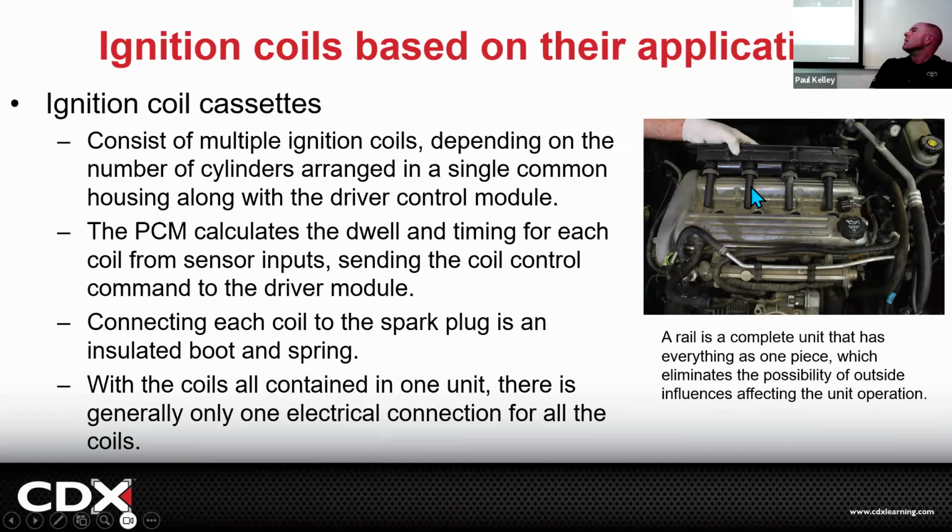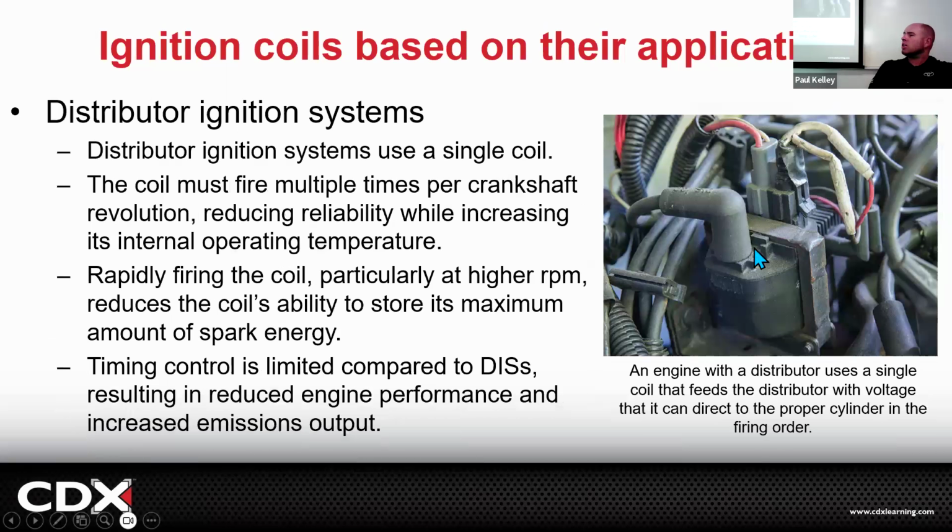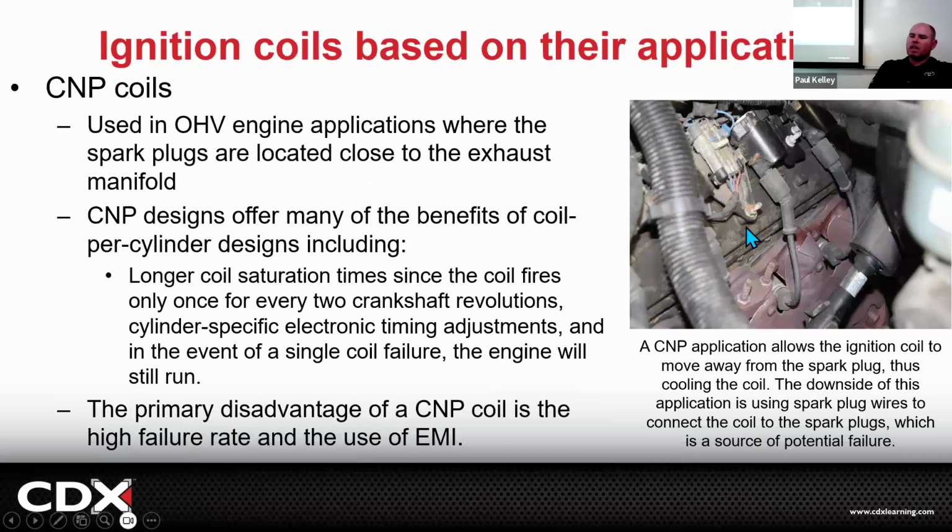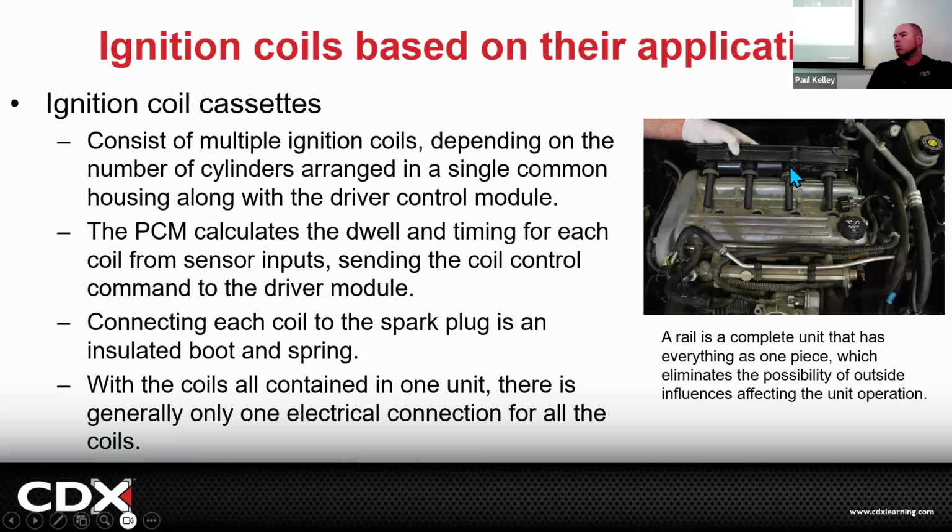And so this one's a little bit of a pain in the butt, though. This might look familiar to you. It's a cassette style. The reason that these were not amazing is because the whole ignition coil and modules and everything were built into the top. So if you had a failure on one, you got to replace the whole assembly, which was kind of expensive. But when it came out, they're like, oh yeah, well, this won't really fail. They were so happy that this didn't need to be replaced all the time, like every few years. They're like, well, this should last at least 100,000 miles. And that was pretty cool at the time. But now you're like, no way, I want to get 250,000 out of it. And then you're shocked when you need a $700 ignition coil cassette assembly.